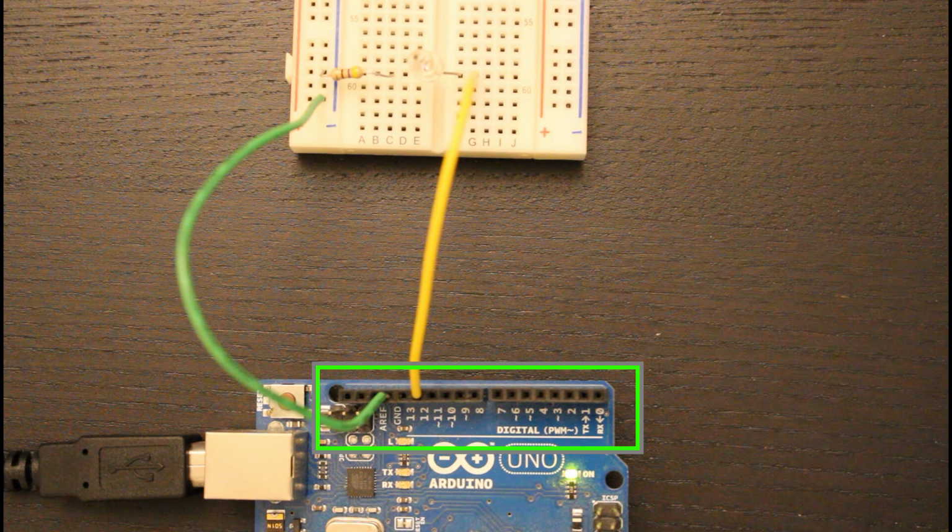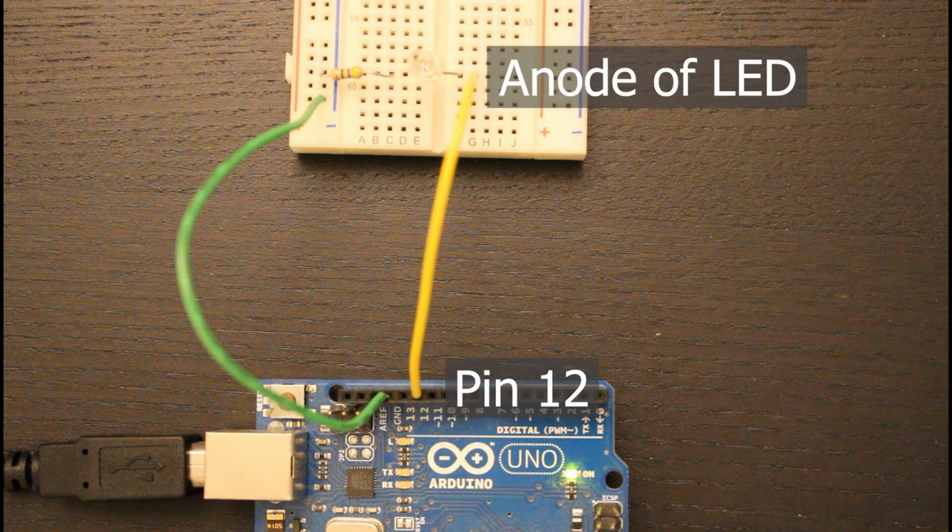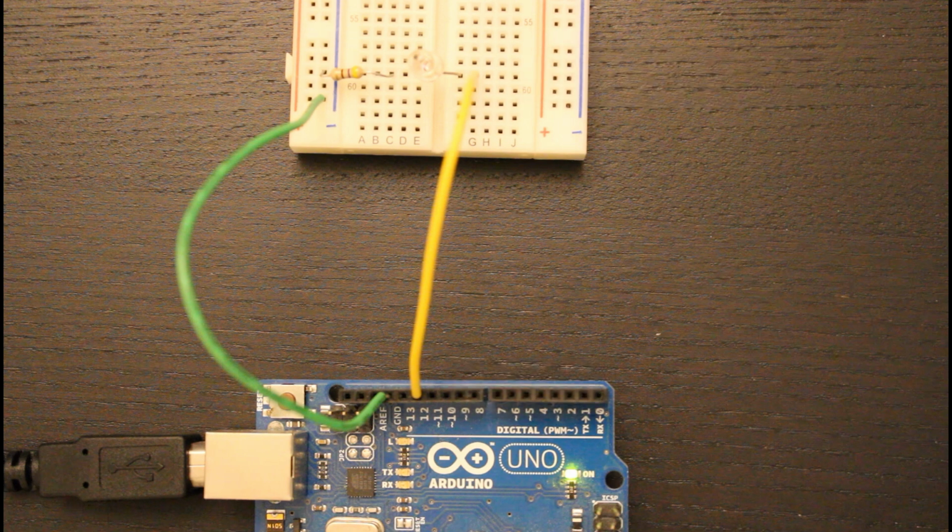You can see that the header is labelled to show which pins it is connected to. And I've connected a wire from GPIO pin 12 to the anode of the LED. The cathode of the LED is connected to the current limiting resistor, which in turn is connected via a wire to a ground pin on the microcontroller to complete the circuit.